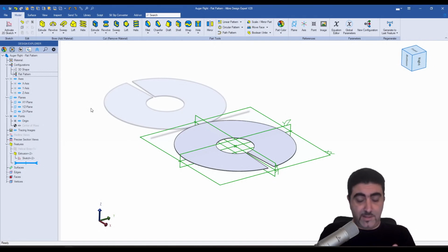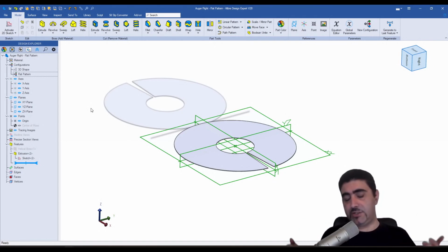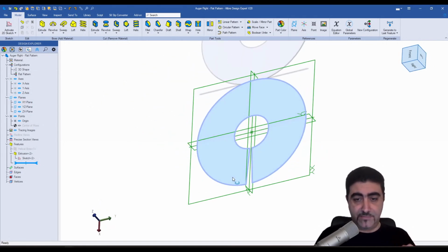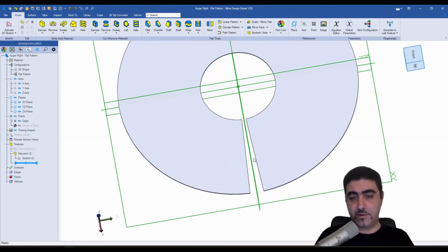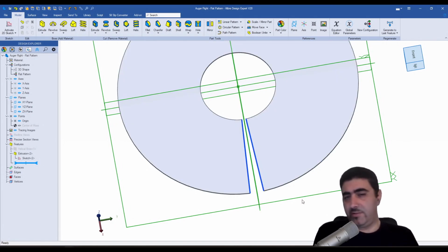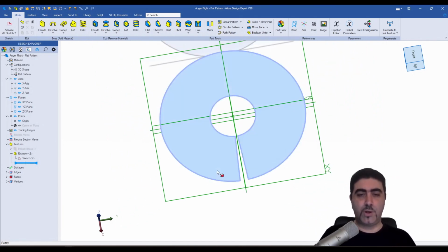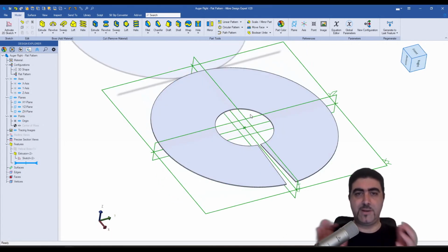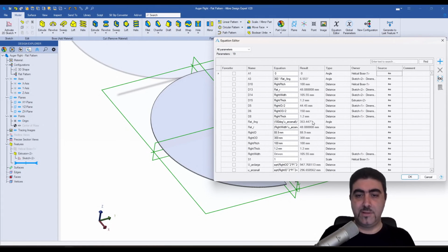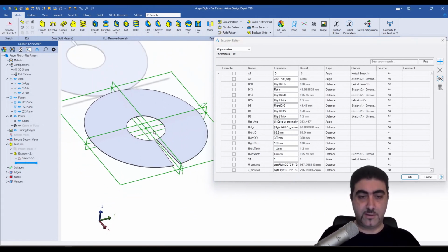Okay, so let's recap. This is the geometric flat pattern. It doesn't take into account stretching, deformations, thinning of the material, all that. If you get this inner angle to be more than 30, 40, 50 degrees, you're pretty close to what the geometric approach can give you. And this happens for large pitch values.